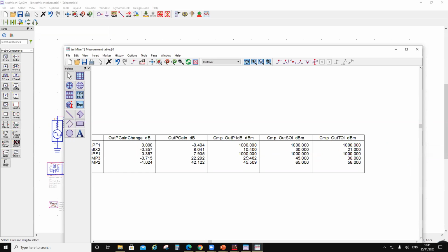So basically, all these different stages, component-wise. So these are cumulative numbers, so you should read them as differences. Well, this is a component to component number. So the 1 dB compression points are over here. For the mixer, it is 10.5. For the driver, it is at 25.5. And for the power stage, it is around 45.5.